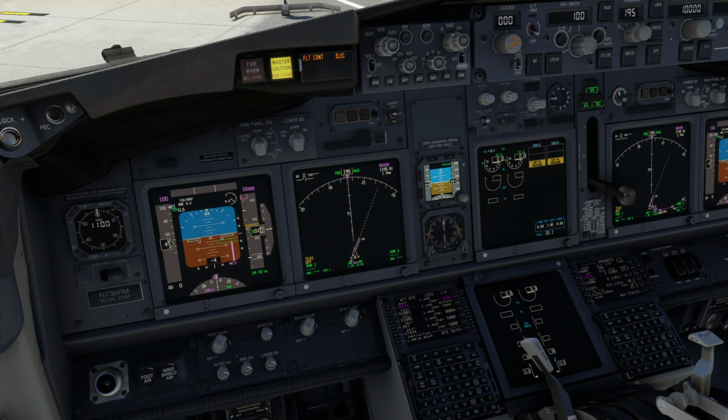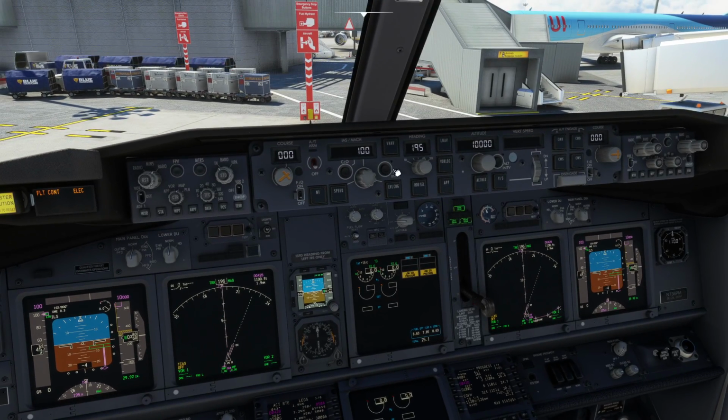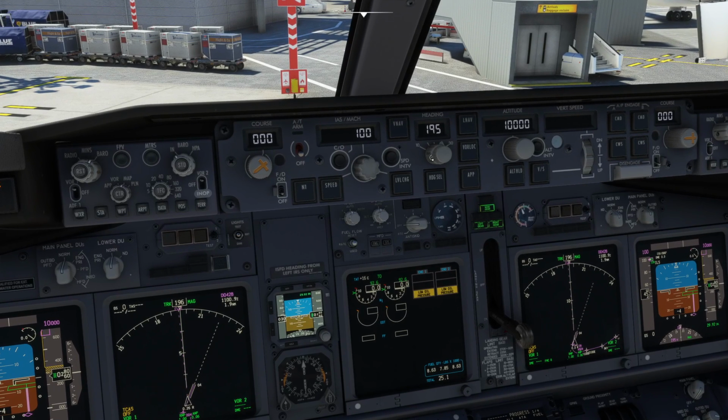What do we need to do then? What haven't we done? Let's go and have a look around. So we've done the flight plan. Next we're going to go to the master control panel for the autopilot. We're going to set it for departure. So runway heading, we're going to set this basically as a backup. We're probably not going to use it. We're going to set it to the same direction as the runway.